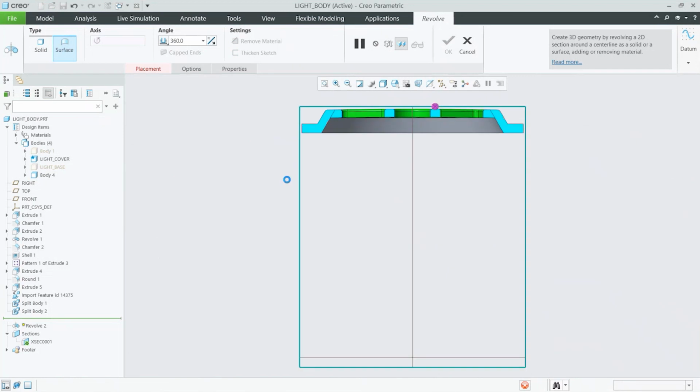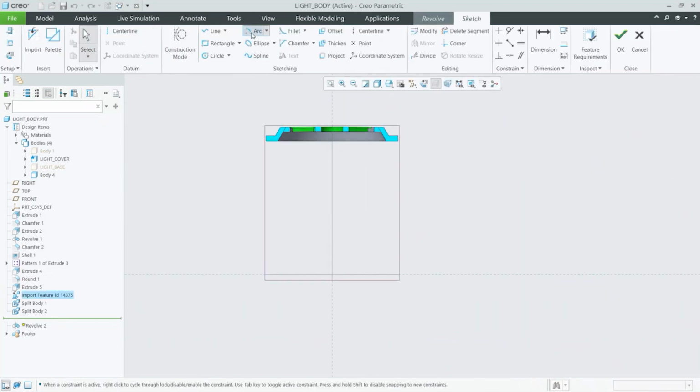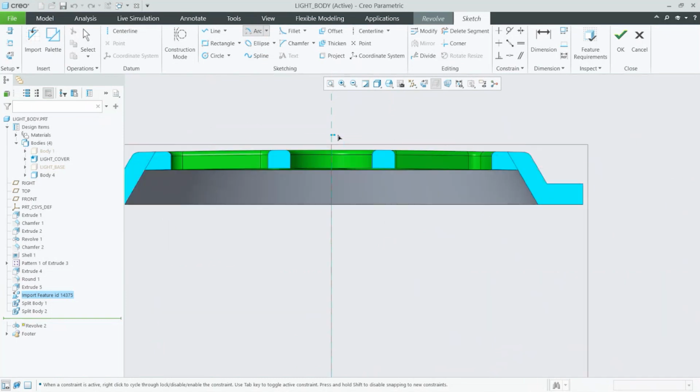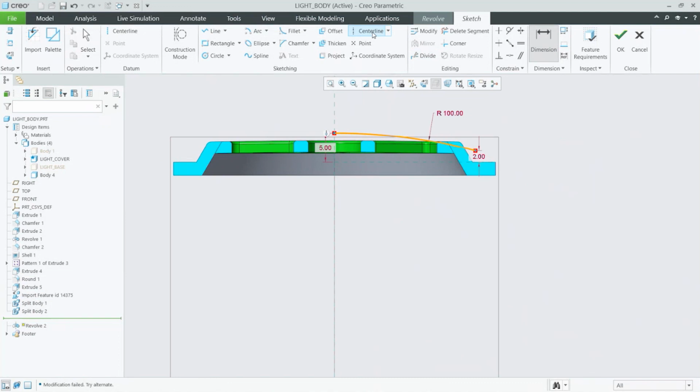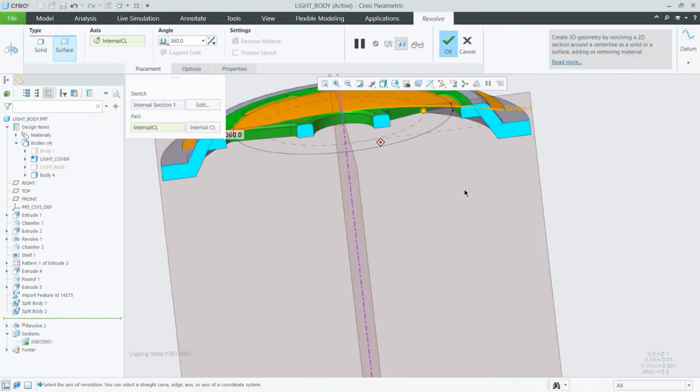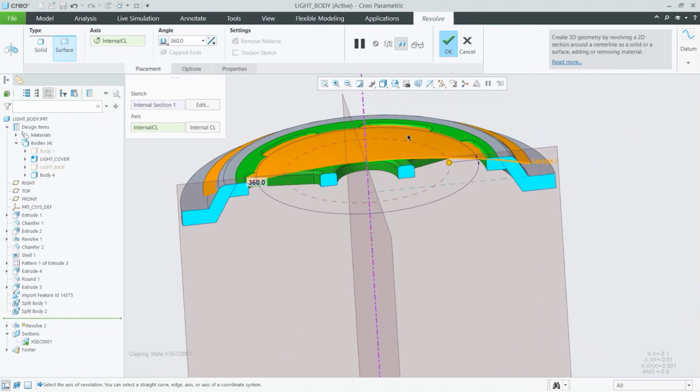For example, this is one of the ideas, the design change you want to make, to make the top a bit bounce up like so. Is it possible? So as a designer, I just simply draw out the shape I want. Dimension change according to the size I want. For example, this is the surface size I want. Draw a center line quickly. So when I say OK, this shape is now revolved as a surface.